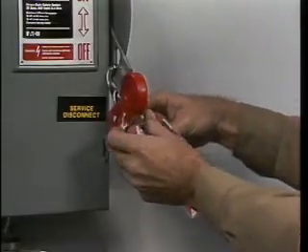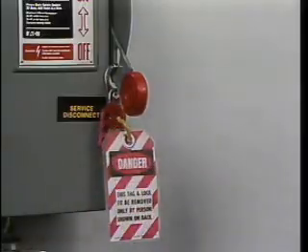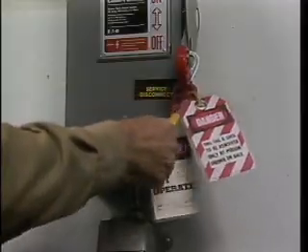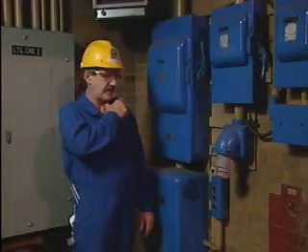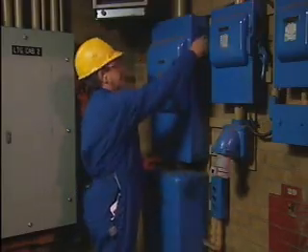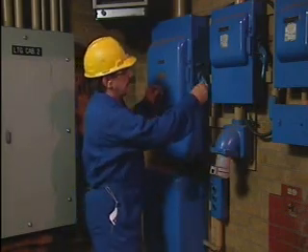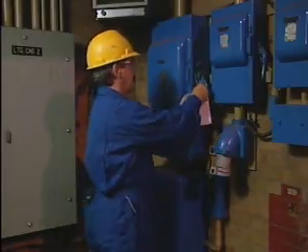In addition, an authorized employee must account for all members of the group and make sure that everyone is protected through all shift and personnel changes. The authorized employee must apply a personal lock or tag to the group lockout device before work is started and remove the lock or tag when work is complete. By following the lockout and tagout procedures in place at your facility, you can help control hazards, and you can perform your work safely and efficiently. Now try a question on locking out and tagging equipment.